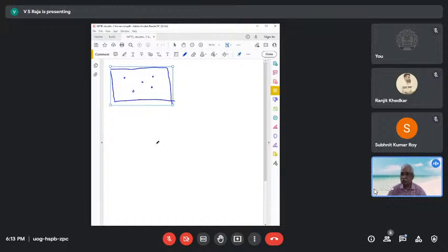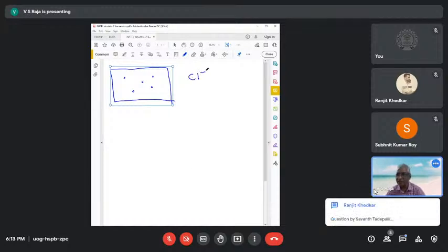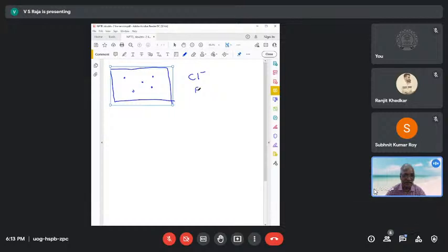The film breaks for two reasons. One reason is you have an aggressive ion. The other reason could be the application of potentials. I apply E, right? A potential E is applied. Of course, one more thing, you can also talk about temperature. And if you want, you can add pH also. These are also related to each other, right? The pH is lowered, becomes acidic, pitting becomes more, right? It happens now.